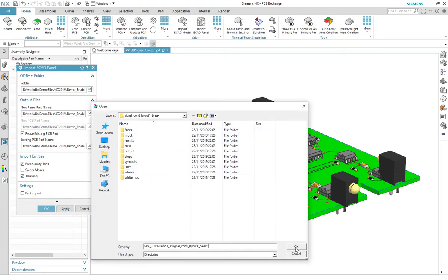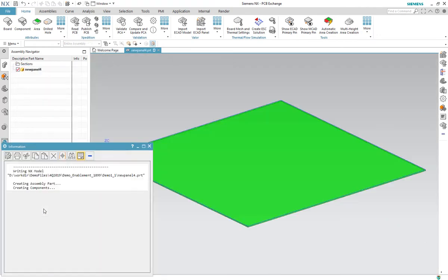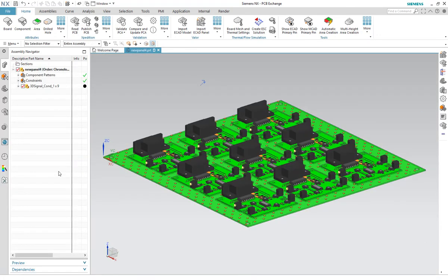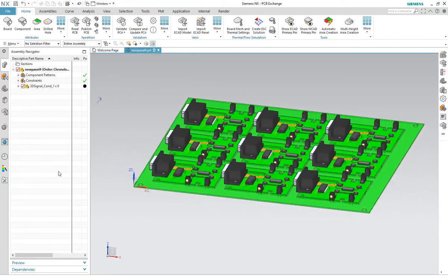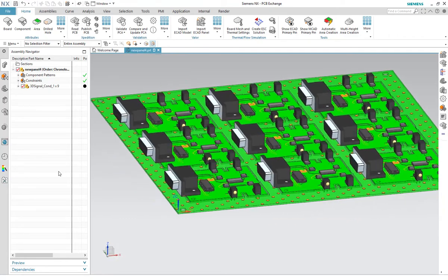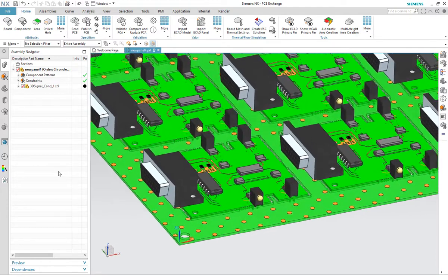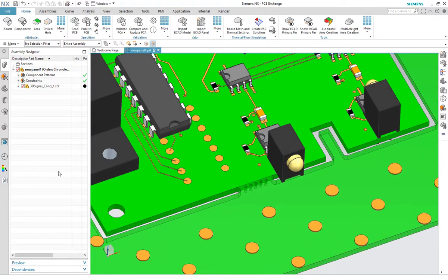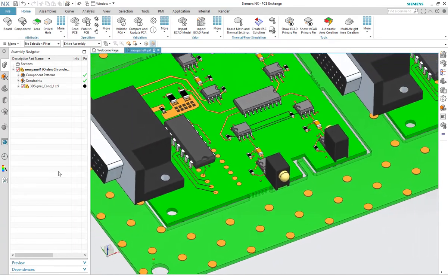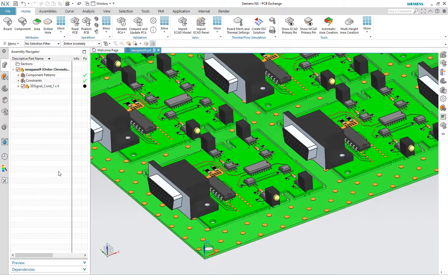The result shows the panel has been created with the PCB repeated as defined and all manufacturing objects added, such as breakouts, thieving and fiducials. Thieving is the creation of dummy pads to provide a uniform distribution of copper to prevent excessive build-up in isolated areas, and fiducials are the datum marks for alignment during manufacture.